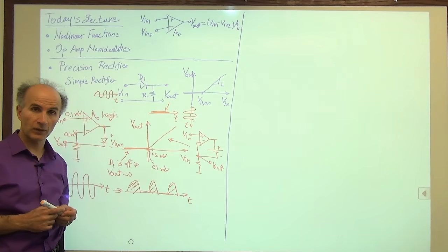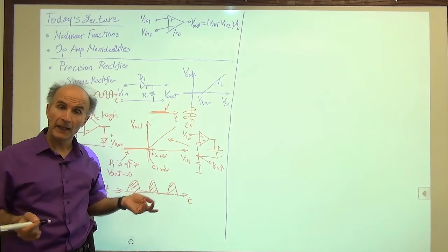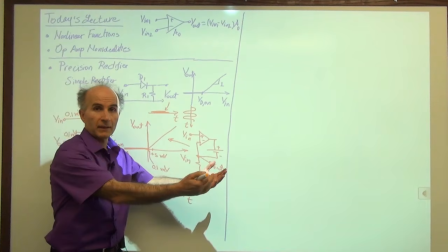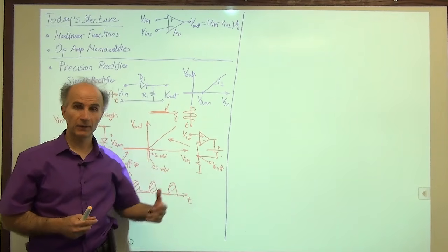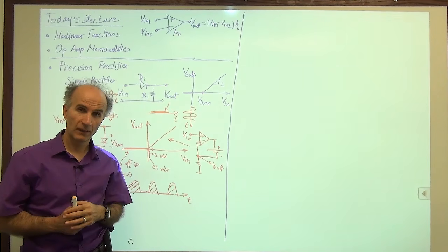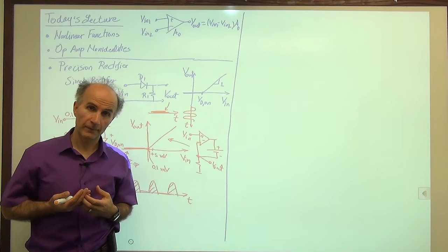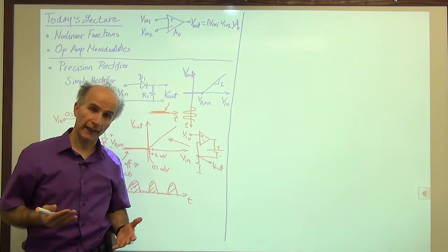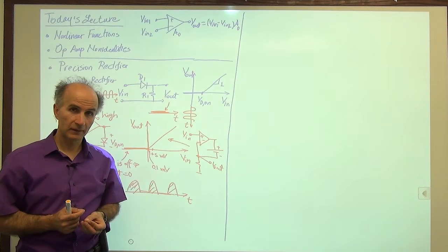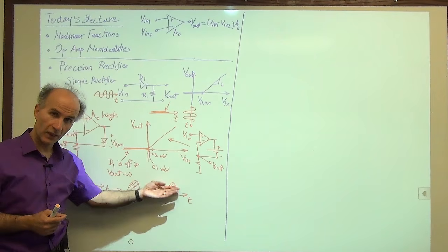This is very useful in cases where, for example, we are receiving a signal through our Bluetooth receiver, and we don't know if the signal is large or small. If you're close to a base station of a Bluetooth or something, or close to another transmitter, then we should have a moderate gain in our receiver. If we are very far and the signal that we're receiving is small, we should have a large gain in our receiver. And the way we determine what type of gain we should have is first by measuring the signal strength that is coming from the antenna. And signal strength means how large this swing is, or how much average we have here.